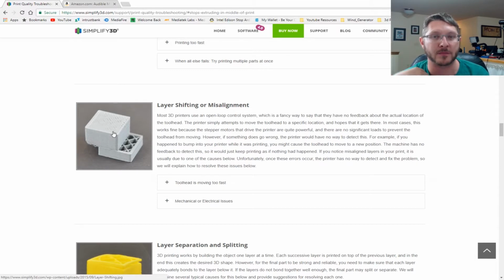Or at least that's what I've experienced, is when a stepper motor will maybe not have enough current to it. Because I know some of the boards, you can adjust the current with little potentiometers on the board. You can adjust how much current, and I think there's G-code for adjusting the current as well. Basically they just don't have enough oomph, and maybe something's getting bound up, maybe the belt's getting frayed, maybe there's not enough lubricant on the linear rails if you're using linear bearings or something like that, and it's getting stuck and it's actually skipping steps, essentially.